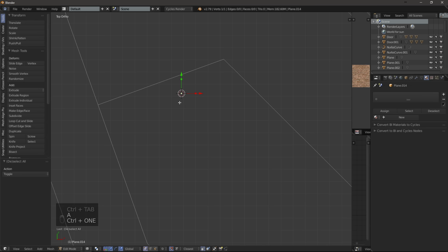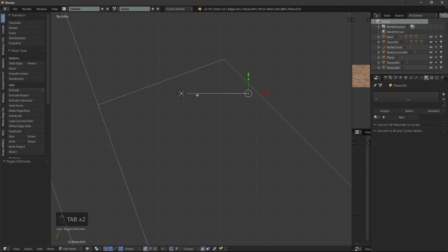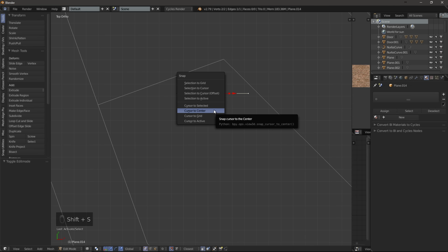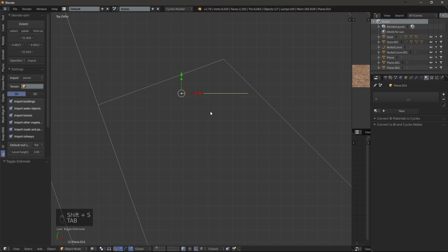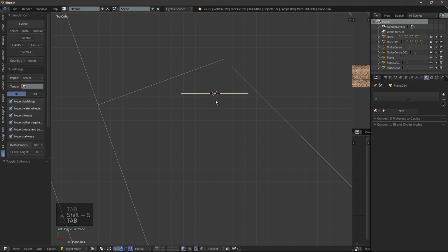There it is. So I start with a mesh. I find that the easiest way to work with curves that are not quite curves, but I convert them into curve data later. I'm just gonna put the origin point in the center here. Nope. Shift S5. There it is. So then I'm gonna convert this to a curve.